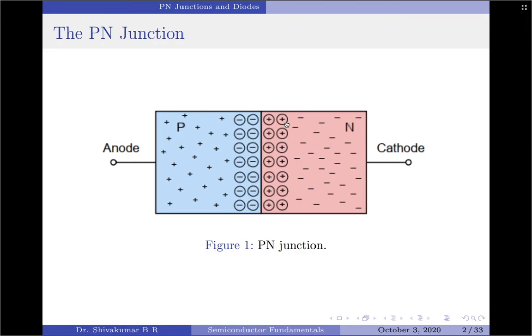The excess electrons of the n material are denoted by minus signs, while the excess holes of the p material are denoted with plus signs. At the interface, the free electrons have recombined with holes. When an electron recombines, it leaves behind a positive ion in the n material and produces a negative ion in the p material. We now have a region depleted of charge carriers, and this will have an effect on the ability to establish a flow of current through the device. We have, in essence, created an energy hill that will need to be overcome.